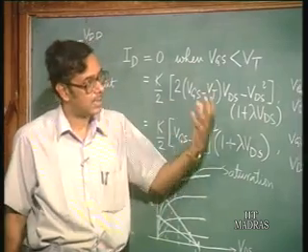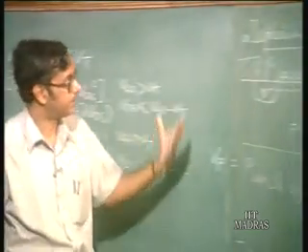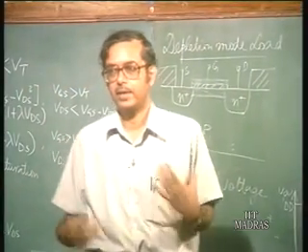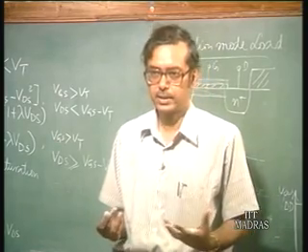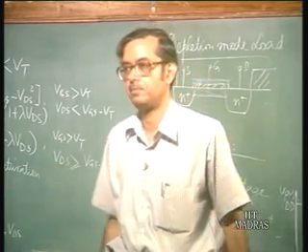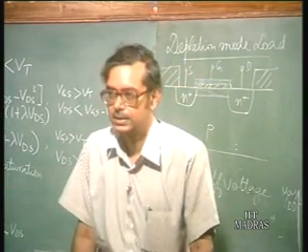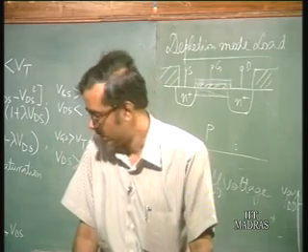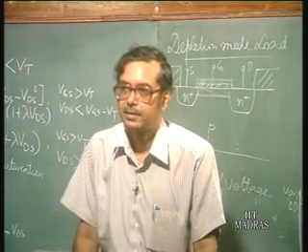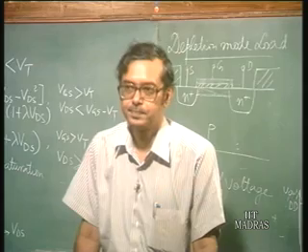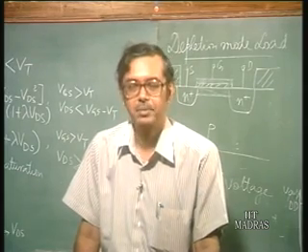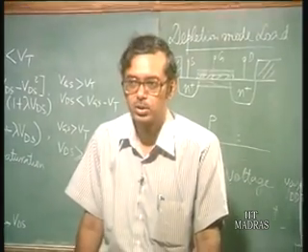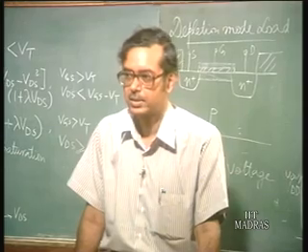This depletion mode load device, we shall see, gives much better characteristics compared to all the load devices which we have talked of so far. In fact, for a long time, a lot of circuits were fabricated using the depletion mode load, till CMOS took over.